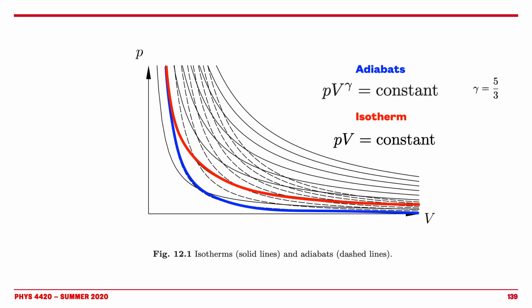So you're going to inject heat in the system during an isotherm, and in fact you're going to have to release heat as well. We'll see that it's impossible to do this without also releasing heat. And we are going to be able to essentially create a cycle on the PV plane by jumping, well, it's not really jumping, from an adiabat to an isotherm, and that's going to make sense.